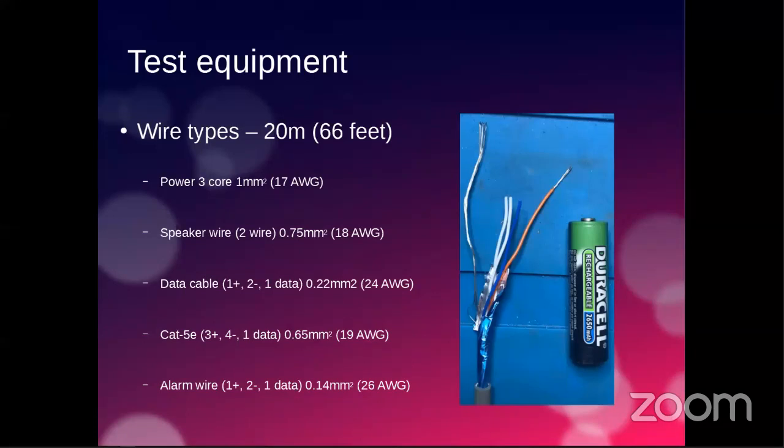Yeah, I definitely have this issue when running floodlights because the lights are spread out further away to cover the house. Right. And they're probably also drawing a lot more current because they're floodlights and they tend to be higher power devices, right? And so your grounds are probably coming up a lot more.